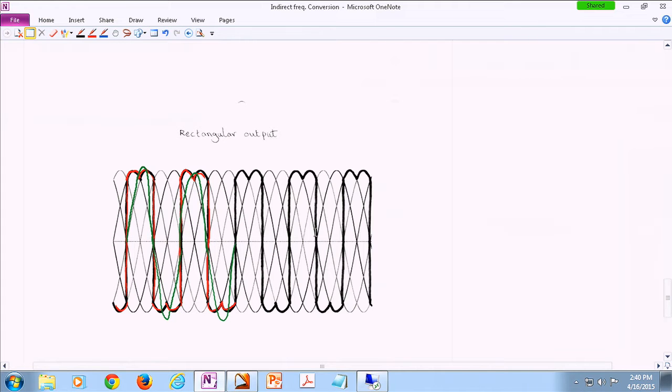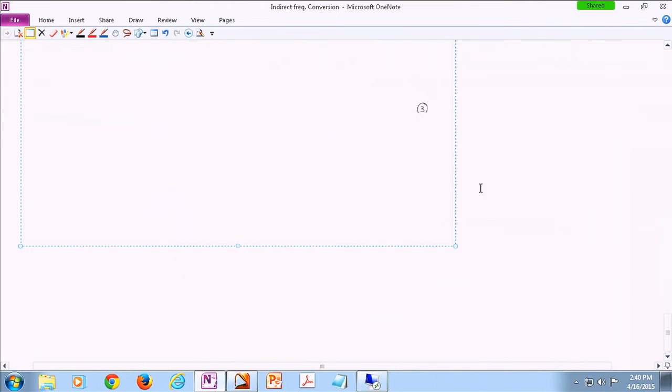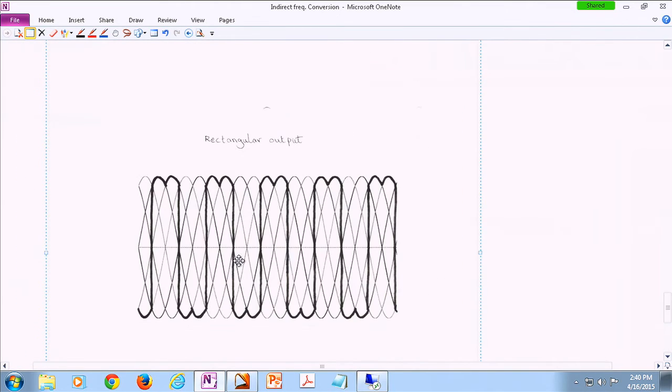The highest that you can achieve without having a very, very messy switching scheme would be, let me see if I can do it over here, something like this. Follow this, then follow this, then follow this. So technically, you can actually achieve an output voltage that has a fundamental frequency that is 6 times larger than your line frequency. Okay, so 360 hertz.